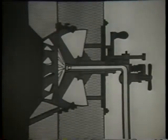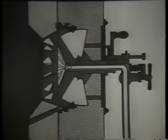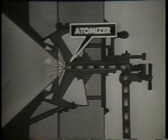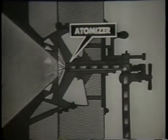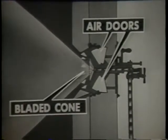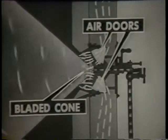As seen in this view of a typical burner mounted in a furnace wall, the burner's atomizer reduces the fuel oil to finely divided mist-like particles. That is, it atomizes the fuel oil. Then the air doors and the bladed cone in the burner register mix these particles with air to form the combustible mixture. Although all burners perform these two functions, atomizing the oil and mixing it with air, different types of burners atomize the oil in different ways.